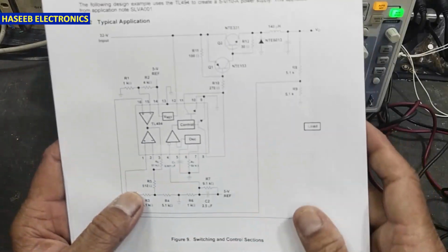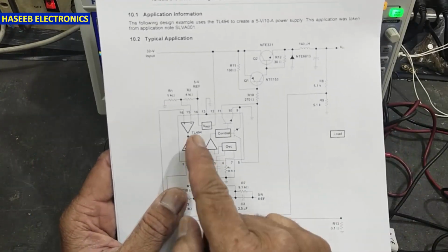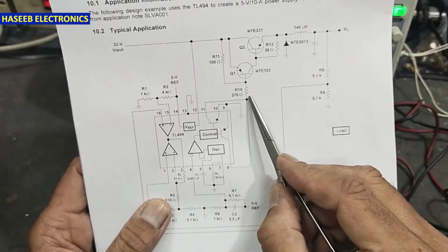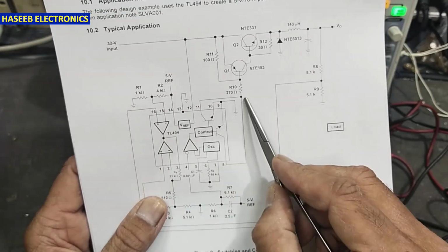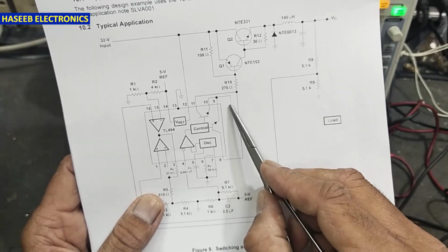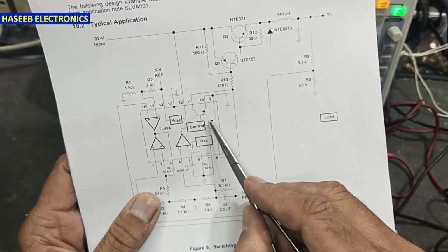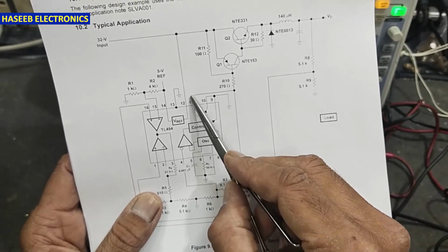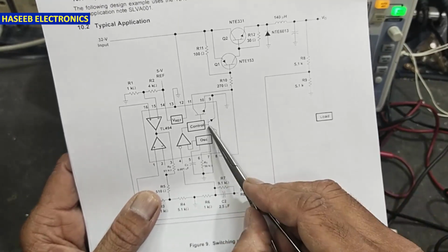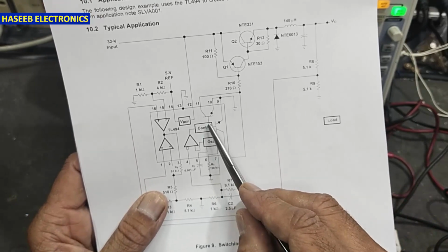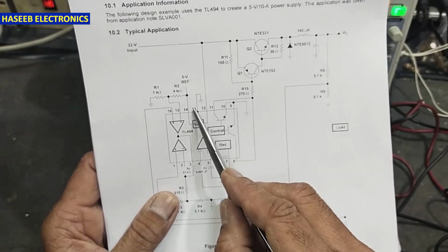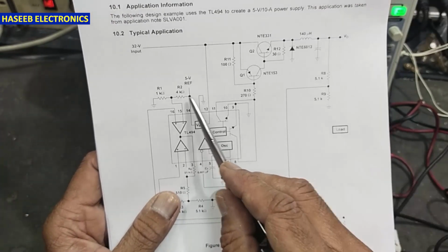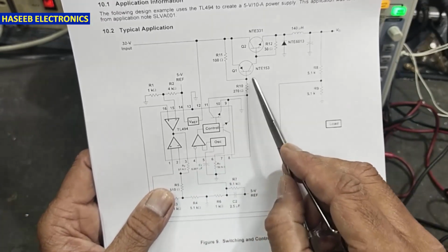As in its data sheet, we can also consult the data sheet. If pin number 13 is connected to ground, at that time both transistors will switch at the same time. If you can see, 9 and 10 are grounded and pin number 8 will drive this transistor and pin number 11 drives in parallel. It is called parallel operation or single-ended operation. If you connect pin number 13 to positive voltage, at that time it will drive in push-pull.